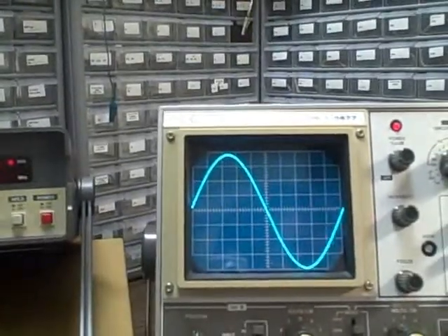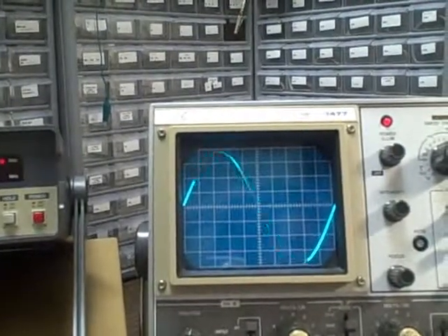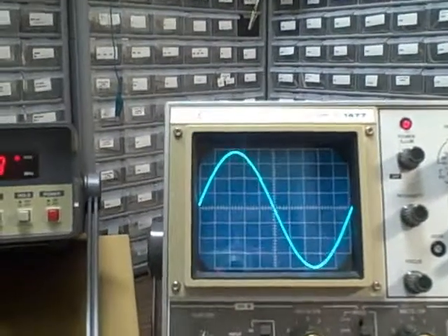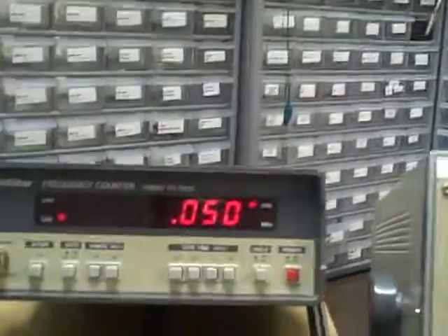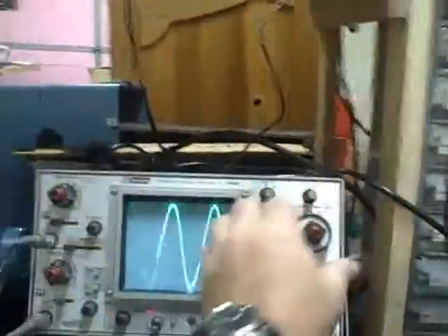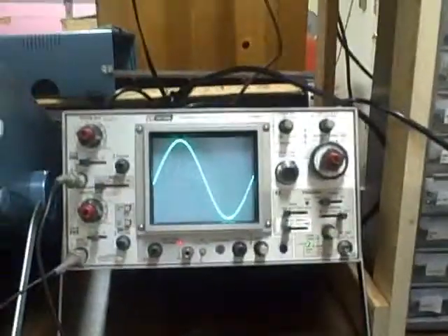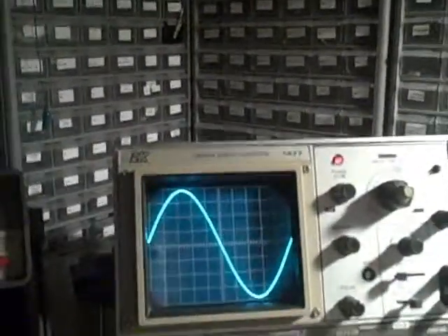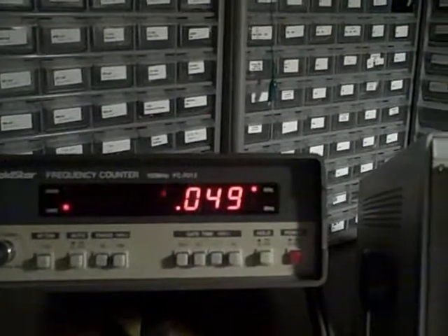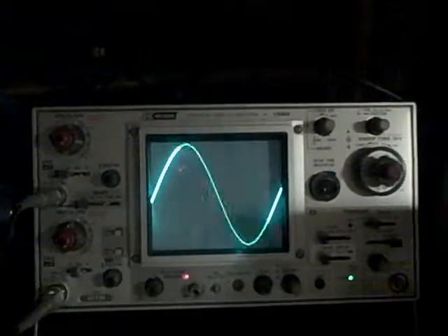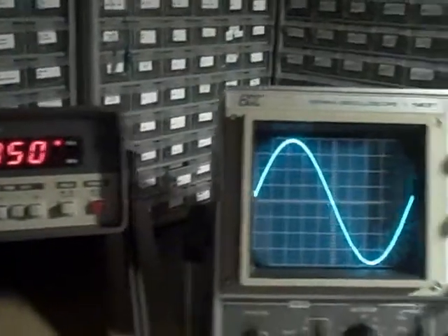And that would mean that at 2 we would need a 50 hertz signal, and right now we are reading a 50 hertz signal, and we need to go up. There we go. Now our reference scope is matching. Okay, so we have a 50 hertz cycle being displayed at the 2 millisecond per division time base setting, and it matches on both screens.